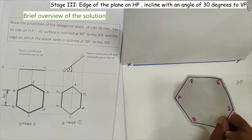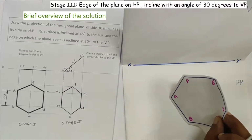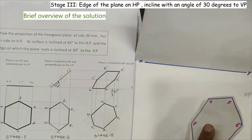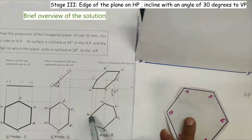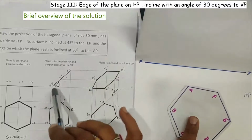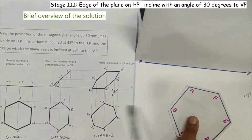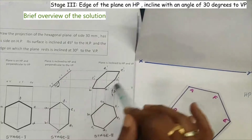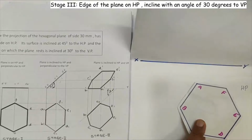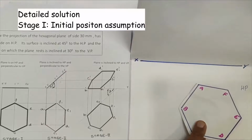Because the plane is inclined to both HP as well as VP, on HP as well as on VP we will get a reduced image of the plane. Here, the side which is on HP, say AB, is inclined at an angle of 30 degrees to the VP and its surface is making an angle of 45 degrees to the HP. With that we get reduced images both in the top view as well as the front view of the hexagonal plane. That's the brief overview of the solution. Now we'll enter into the detailed solution.